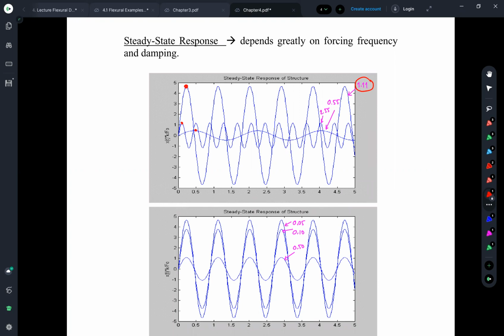And another partial safety on the material properties is the reduction of the strength. We often find something like a reduction for the columns. When you compute the nominal capacity of the column, we should multiply it by 0 point something, maybe 0.5. Okay, let's say 0.5. So in total, the safety factor that we have in hand, I think, is not greater than 3. It's about 2 point something to 3.